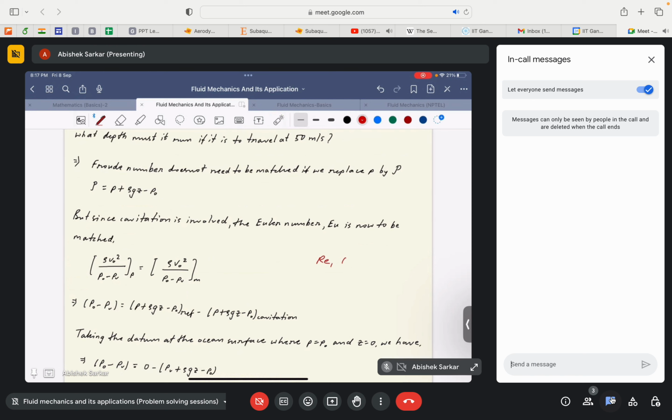We will have Reynolds number and Euler's number, and we would have incorporated Froude's number in Euler's number. So that's simple. But that's not actually what it conceptually means. It basically means that the effect of Froude number is being incorporated in the pressure gradient term that is dealt with while non-dimensionalizing, and that is incorporated in the Euler's number. So that's what it actually means.